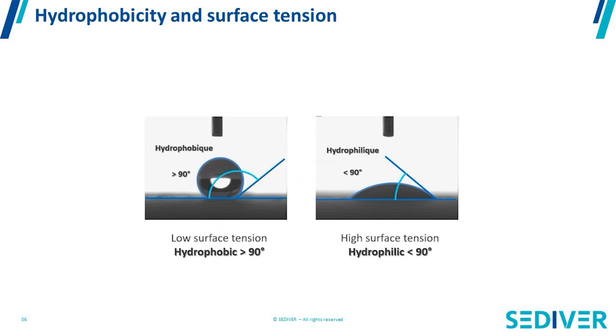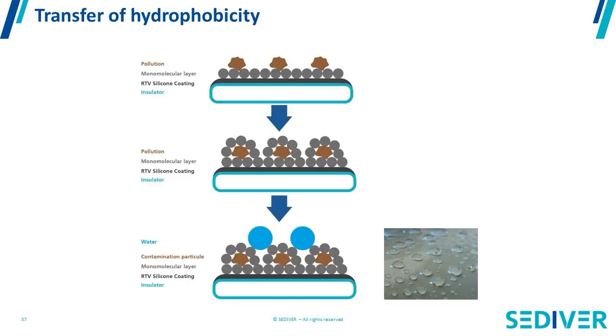So when you use a silicone surface, which can be used either with what we call polymer insulators, which are insulators made of silicone rubber, or a silicone-coated glass insulator where the surface is made of silicone rubber, you benefit of this property called hydrophobicity, so that the insulator remains dry and will have a better pollution performance.